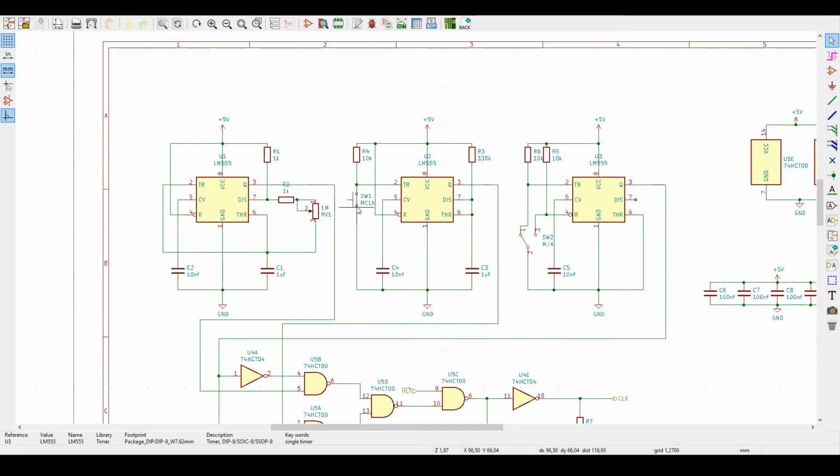So as soon as the first contact is made on the switch, the timer starts to charge this capacitor, and the output is held high. And when the capacitor reaches the threshold of 2/3 of the voltage, then it is discharged again and the output goes low. And I've calculated this time constant to be around 1/3 of a second. So it's more than enough to get rid of any noise created by the switch.